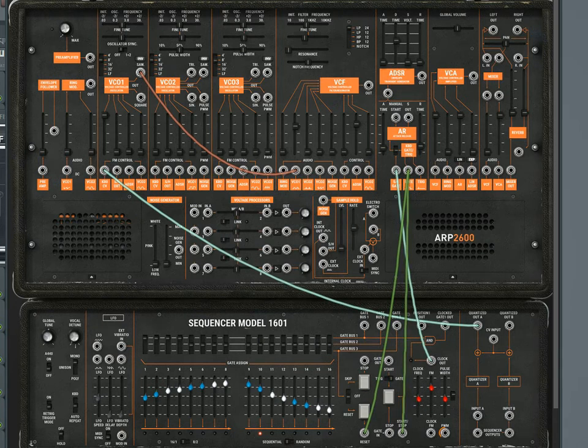One of the ways that we can use this is to add swing to the sequence. So let's set it up so that gate 1 is on for every other note of the sequence. And we'll lower the FM amount to a fairly low level. So what should happen now? Now the clock of the sequencer speeds up every other note of the sequence, and the effect should be that every other note is a little bit shorter than the previous note, and that should give us a little bit of swing. Let's see what happens. Just as we expected.